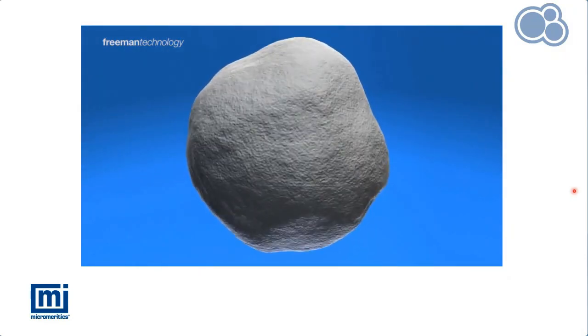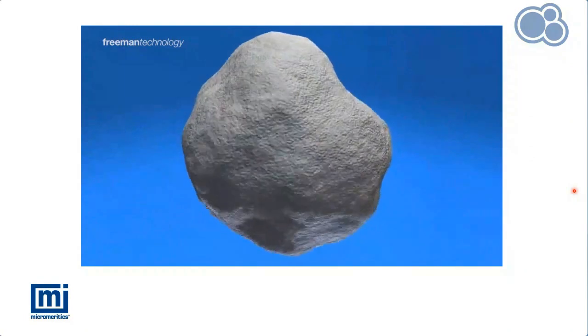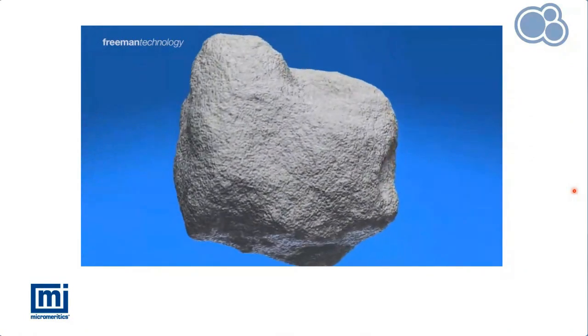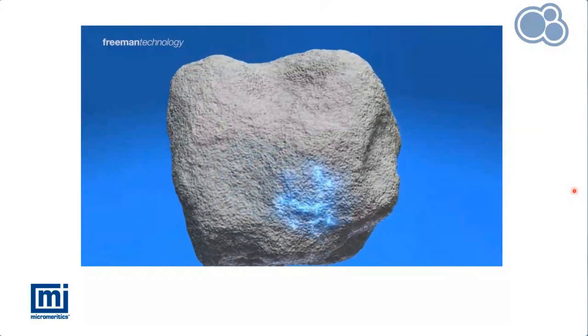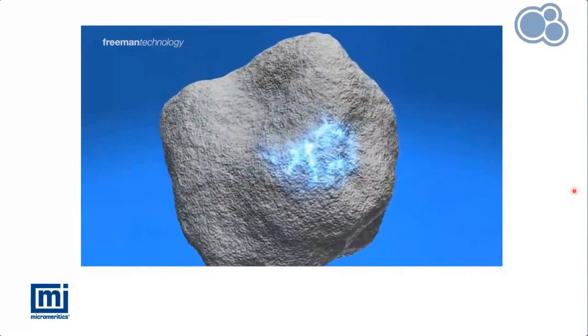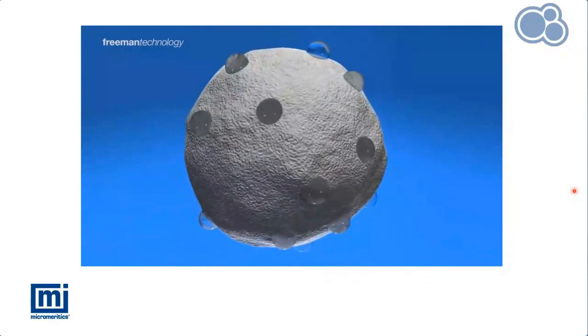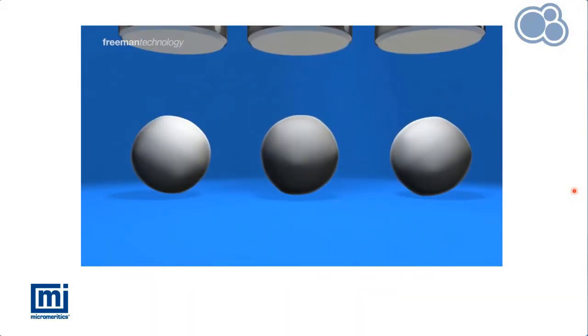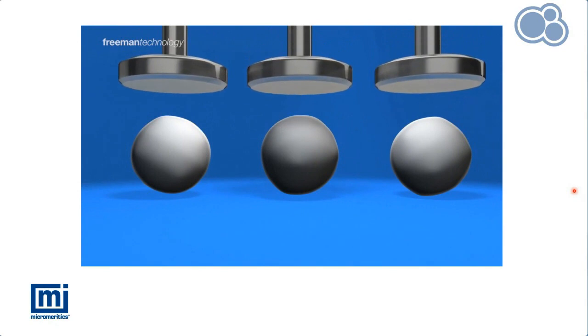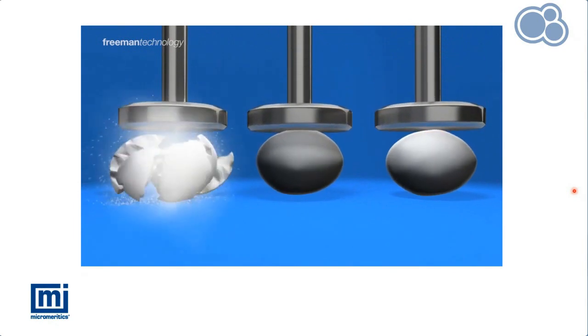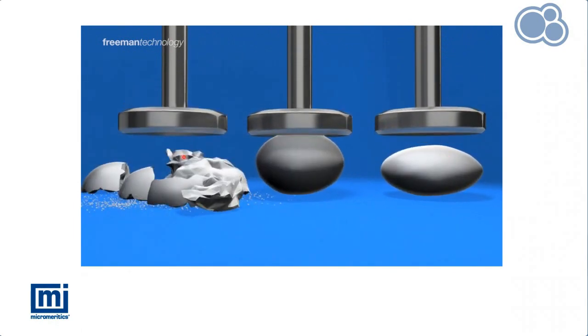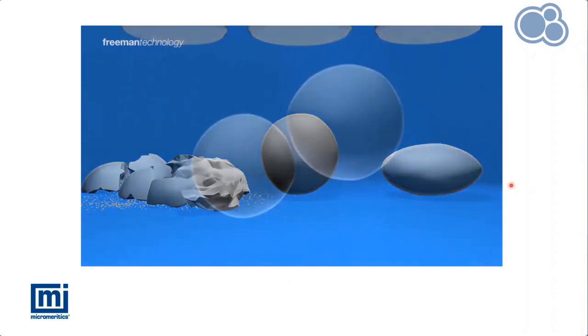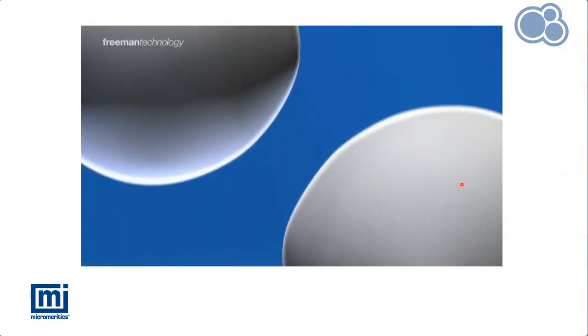Other properties to consider as well: the surface texture, the shape of the particles, if there are any electrostatic forces between particles, if there's moisture on the surface of the particles that could lead to capillary bonding, and also if the particles are friable, if they're prone to attrition, like we saw in a particle on the left, or if they're prone to any sort of deformation as well.